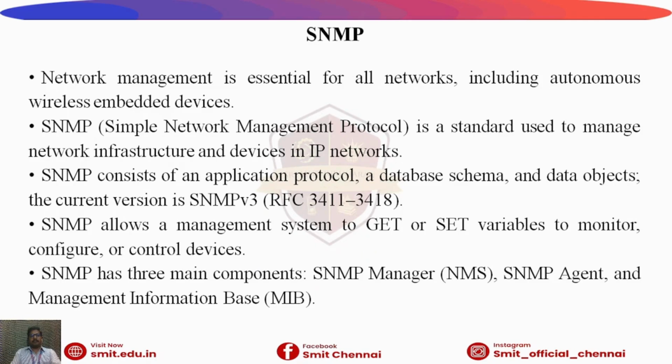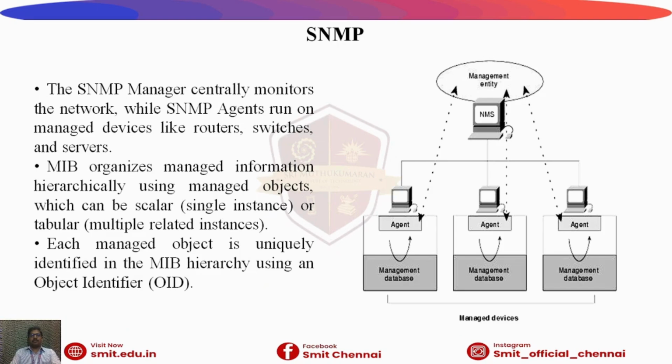Then SNMP. SNMP is a standard protocol for network management and monitoring. Network management is essential for all networks, including autonomous wireless embedded systems. The expansion of SNMP is Simple Network Management Protocol. It consists of SNMP Manager, SNMP Agent, and Management Information Base, which is shortly called MIB. SNMP allows get and set operations to retrieve and configure device parameters. SNMP v3 provides enhanced security features. It is useful for managing embedded IP devices.